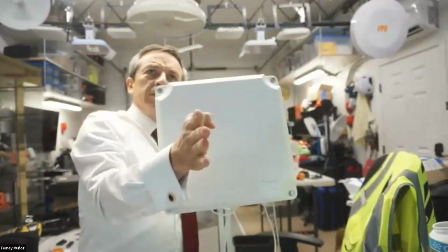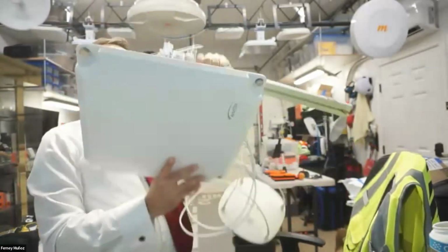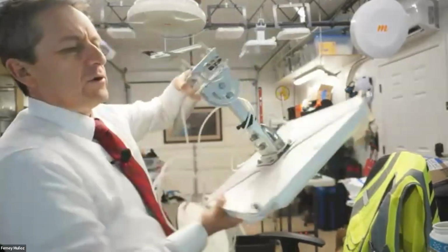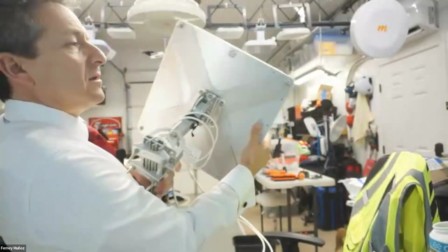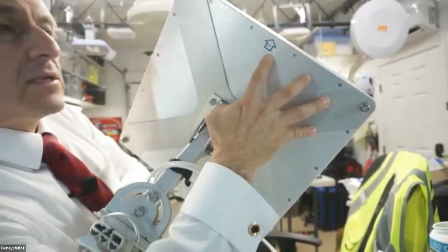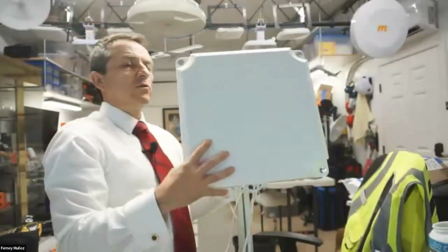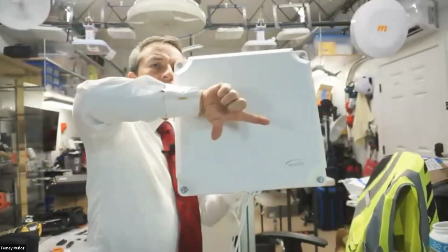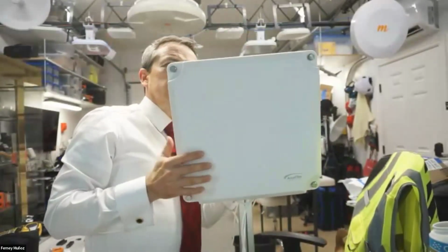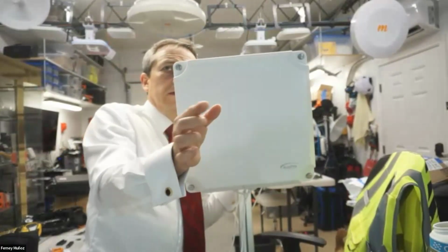If we turn the antenna over, then it's going to be doing this. If we put it on the ceiling, shooting straight down, then depending, see the orientation, it has the up arrow on the back. Right here it says up. I don't know if you can see it on the picture, on the camera, but that says up. That's how it is designed to be mounted, like this. The horizontal is 15 degrees. The vertical is 120 degrees. This is designed to shoot down the aisle at a narrow beam width, okay?